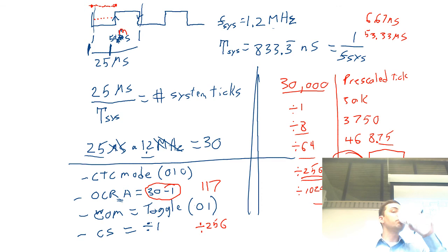I think that's it. All right, so this is for waveform generation. So there's that first divide by 2 that you have to address. If you gave me this for 25 microseconds, I did 25 milliseconds for my calculations. So if I was just asking you to do a delay, you wouldn't have to do that divide by 2 shenanigans.